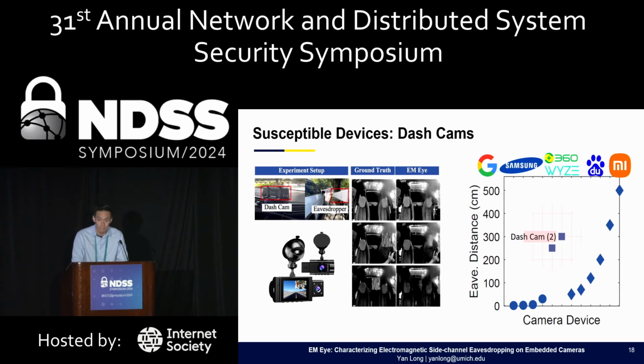Thanks. That was a fantastic talk. Nader Sabash, UCLA. For these cameras, I noticed the leakage was around 200 megahertz. Was it the same for all the cameras, or was it significantly changing? It's a very wide range. I would say it starts at about 100 megahertz or even 50 megahertz, and you get these harmonics because they are transmitting bits as square waves.